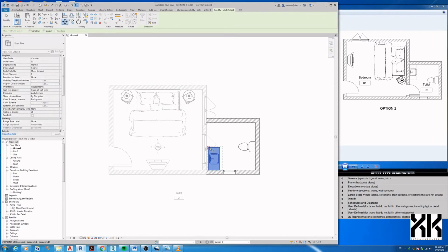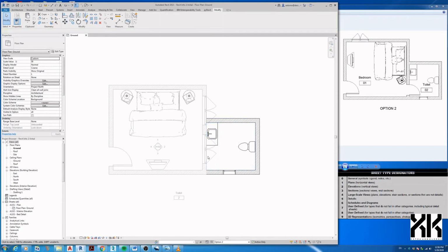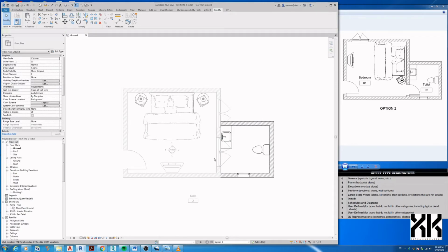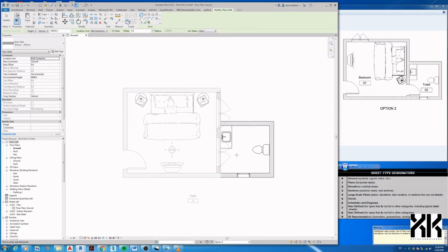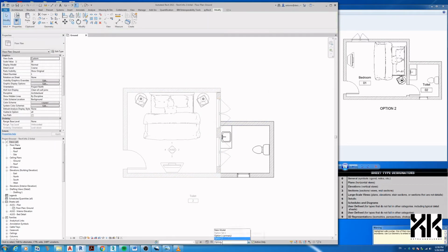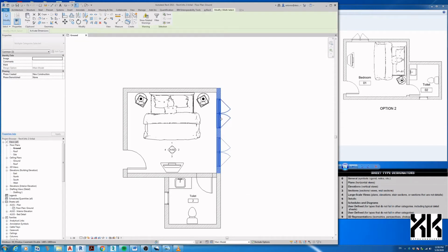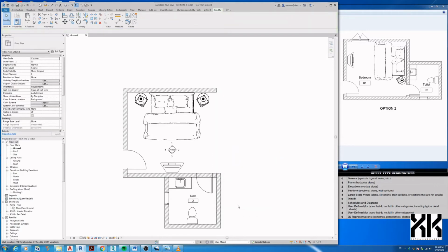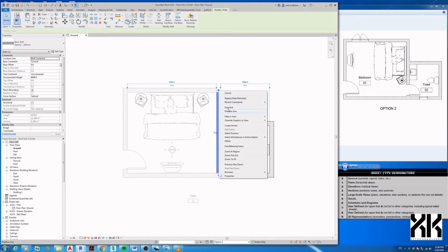Again, we need to draw a door in this wall. Instead of using this wall, as we have discussed, create a new wall as intended. Then hide the wall, including the windows, from the main model. By going back again to the main model, select the elements, right-click, Hide in View, Elements. Back to option 2, fix the wall if needed, and draw the door.